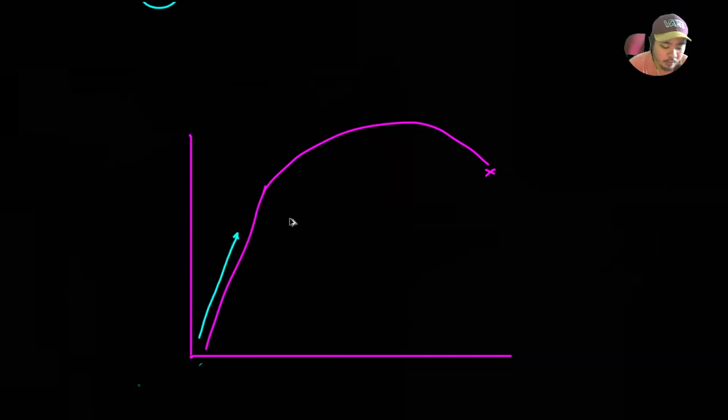Now what happens if we do the straining and reach the point of yield? So we are in the plastic region. It has passed the yield, so we now have plastic strain, and we reached up to here. Then we unloaded the load cell. Unloading means we stopped the test and allowed the metal to return to its original size. What actually occurs is that if I draw a line parallel to this linear portion, I can determine which part it will recover.